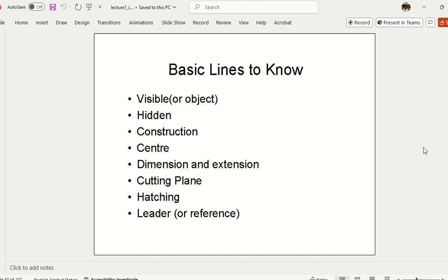So you put these lines. Now where are these lines? At the end of my object, right? This is my object, and I have two lines at the end. These lines are called extension lines. These vertical lines are called extension lines. And what is this, the line with the arrows? This is called the dimension line.